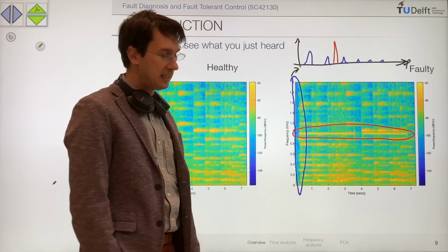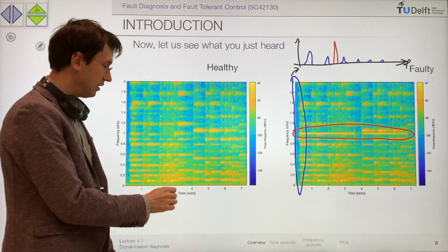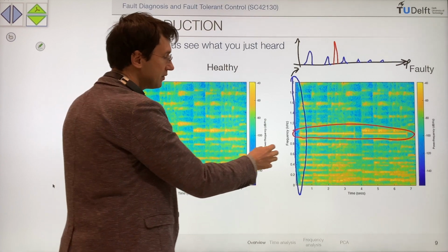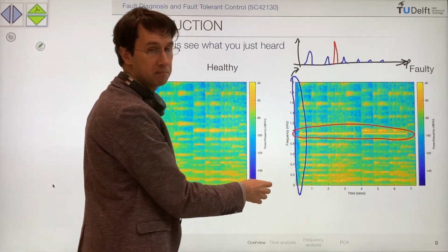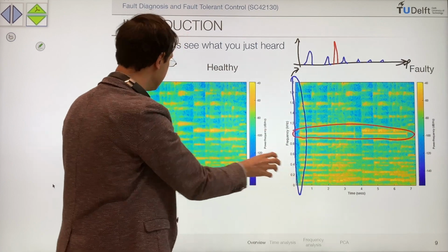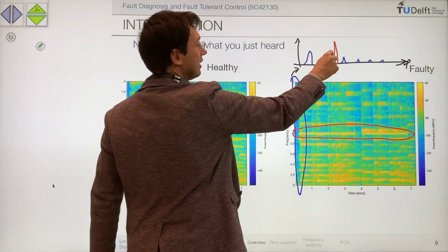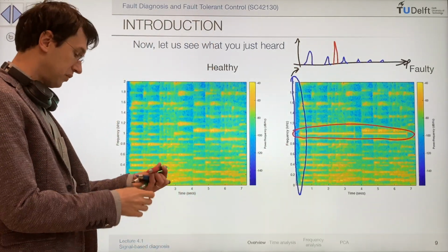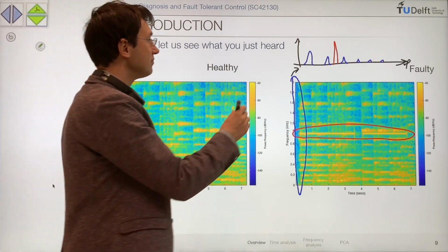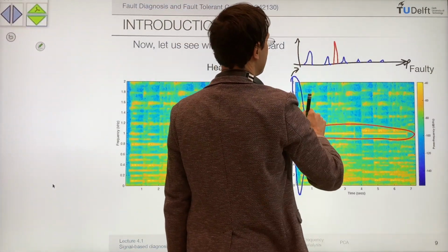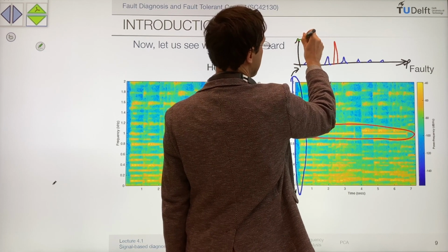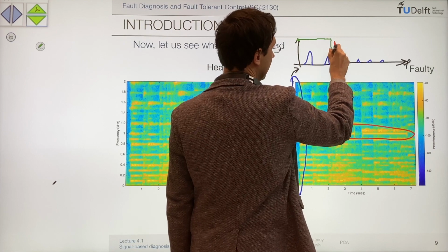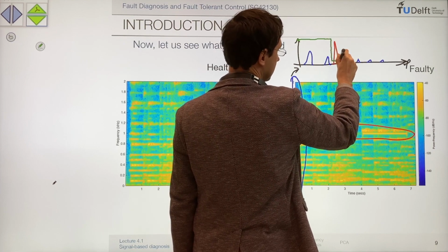So a way of detecting this is, first, to have a knowledge of what is the nominal behavior, and then we can simply compute the difference between what we get here and the nominal, and then this peak at this frequency will stand out immediately. So what we can do is to have a threshold for this frequency component. Normally you allow sound amplitude at this frequency, but here you know you need to have silence or just background noise.